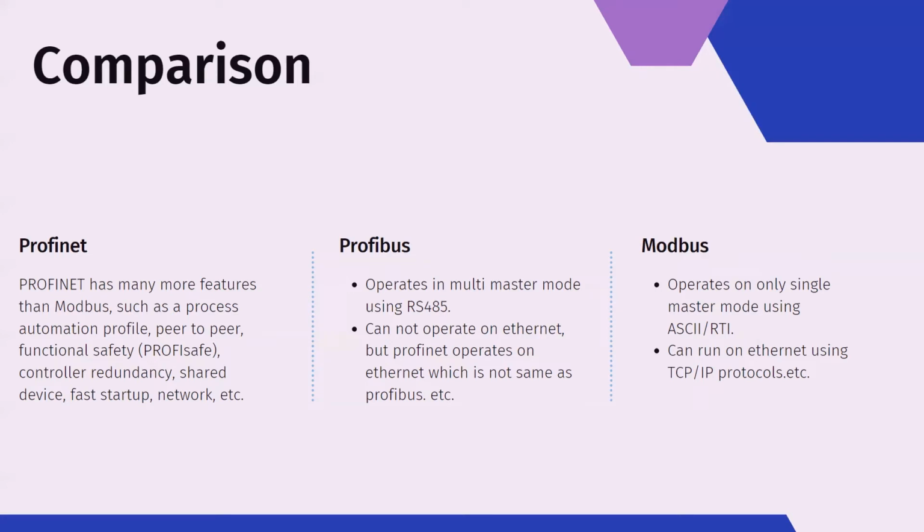As for distance coverage, 32 stations use Profibus for distances up to 1,200 meters, while 2 stations communicate at speed of 500 kilobits for distances up to 400 meters. Low-speed transmissions support higher distances, while high-speed transmission supports lower distances. Modbus cable should be less than 700 meters.